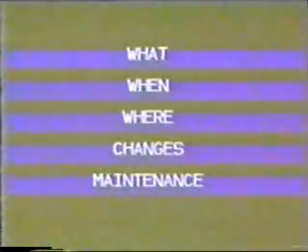Where did the problem occur? Has the operator made any changes in an attempt to correct the problem? When was the last time maintenance was performed on the packing? Further checks in maintenance logs may provide additional information.